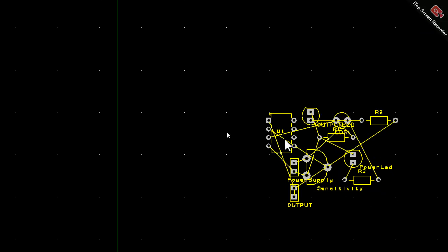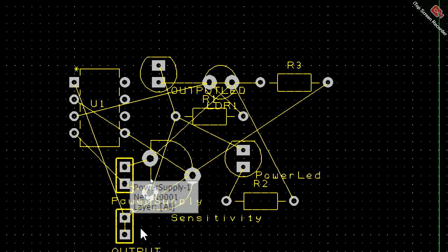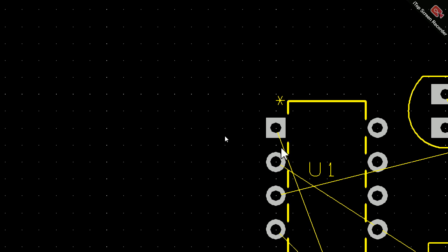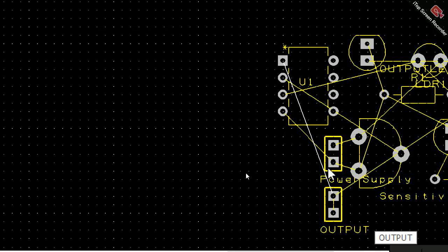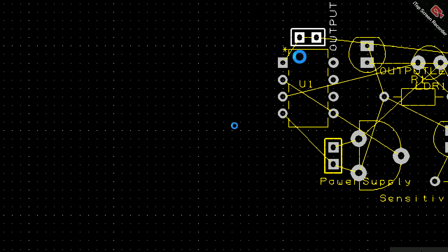Now it's time for us to place them properly. This is a very important skill. See here, you have to start from the first pin. Click on first pin, first connection. You can observe it becomes white color. Bring the component which is connected to that. Rotate, R for rotation. Place it near this.